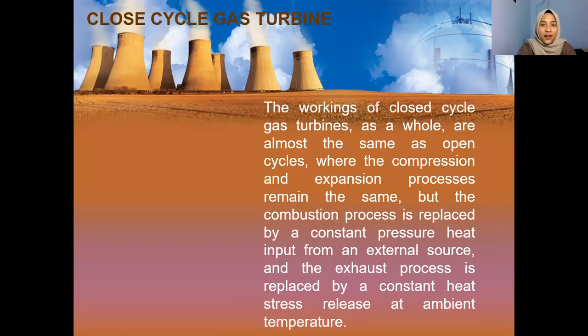And then the closed cycle gas turbine. The workings of the closed cycle gas turbine as a whole are almost the same as the open cycle, where the compression and expansion processes remain the same, but the combustion process is replaced by a constant pressure heat input from an external source. And the exhaust process is replaced by a constant pressure heat release at ambient temperature.